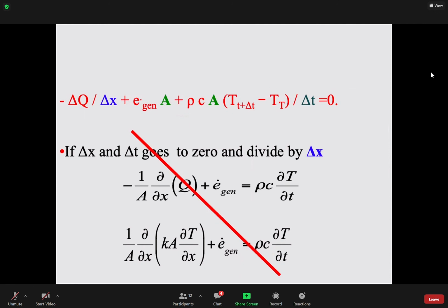Yes. And that's exactly what we had in building science. Remember the cooling load factor? Remember, my friend? Did you pass that course? I think that's why I'm here. No, I'm joking, my friend. The cooling load factor, that's exactly what happens here. The maximum solar radiation is at 10 o'clock, but the effect on the room temperature appears at 2 o'clock in the afternoon. We call that the time lag.